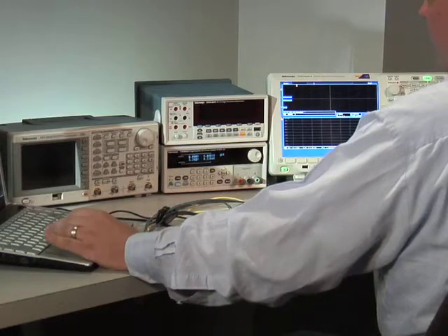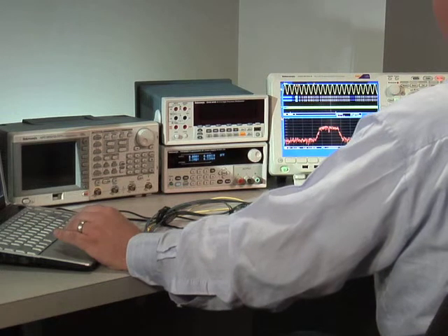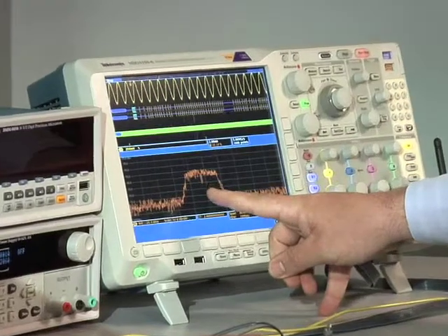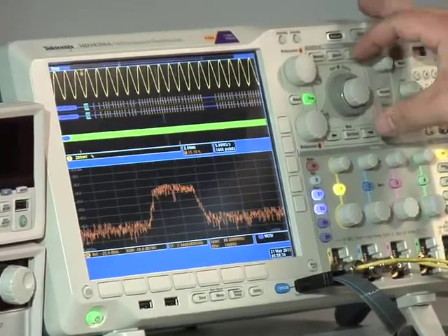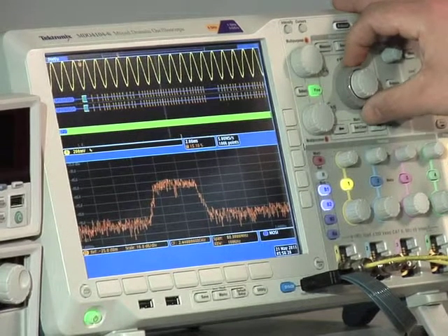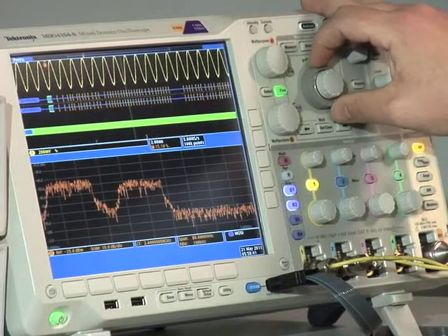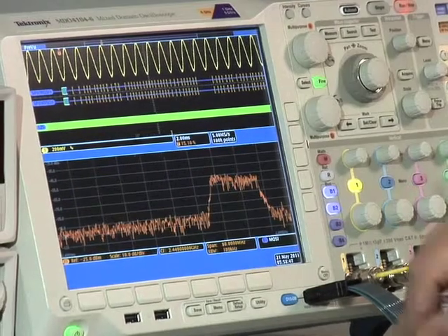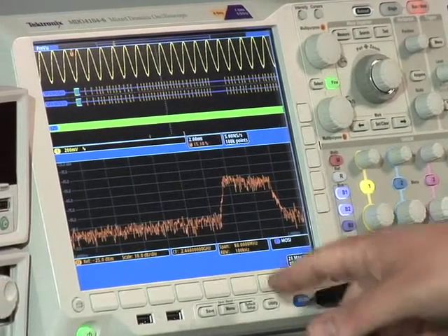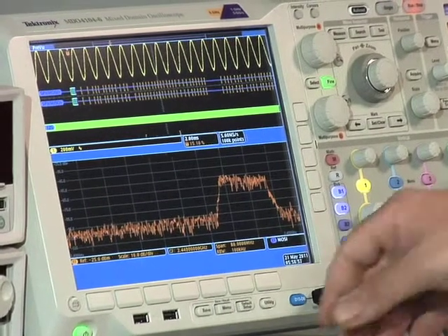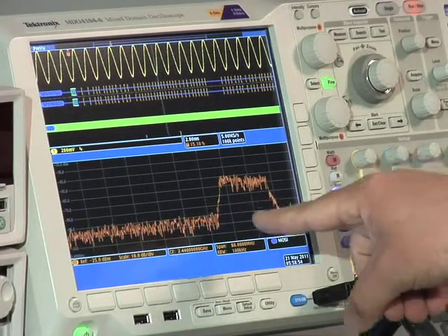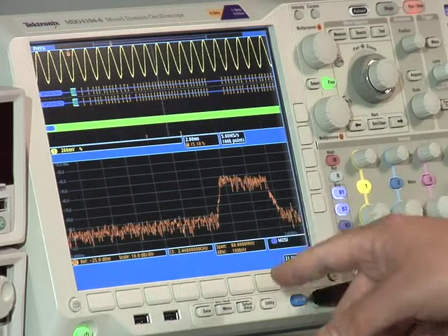The scope is triggered. This is my original frequency. You can see I'm in the middle of the band. I use the pan knob to shift my spectrum time over to the new frequency. And I did see an interferer pop in there as well when I was navigating around, one of the consequences of working in a live environment. So here's my second frequency, the high channel.